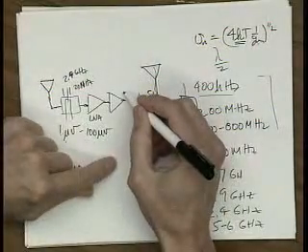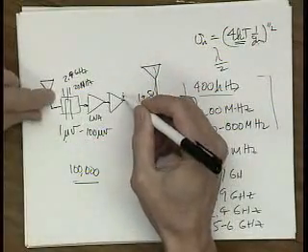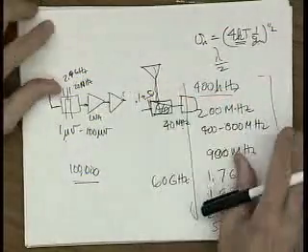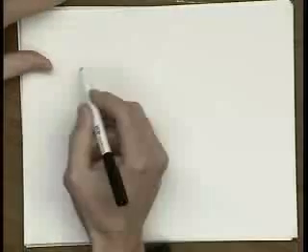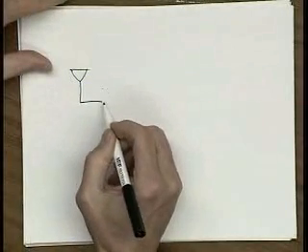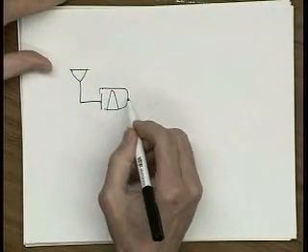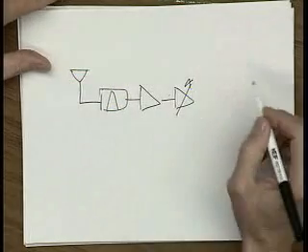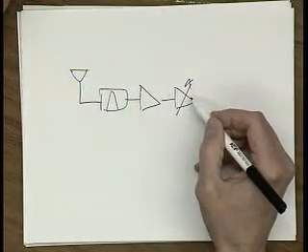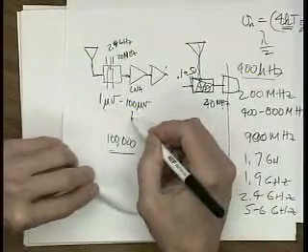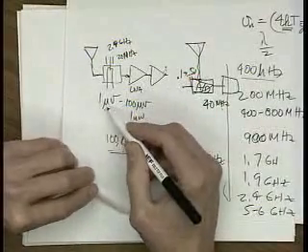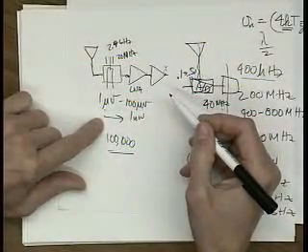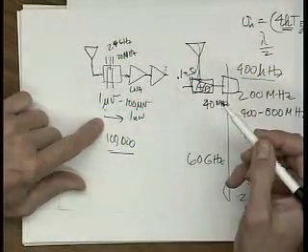So you've got to have some more gain stages, and you usually alternate gain with more filtering. So here's our antenna. Let me start again here. A filter, LNA, more gain, and often you have to make this variable gain too, because sometimes the signals will be 100 microvolts, maybe a millivolt sometimes, sometimes a microvolt. So the signal itself may change over a factor of 1,000, and that's the big problem with RF radio design.